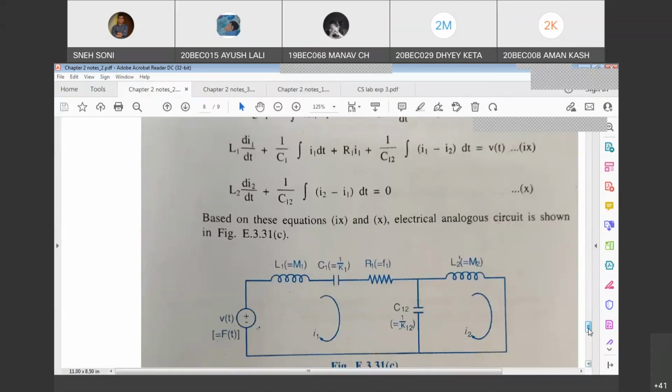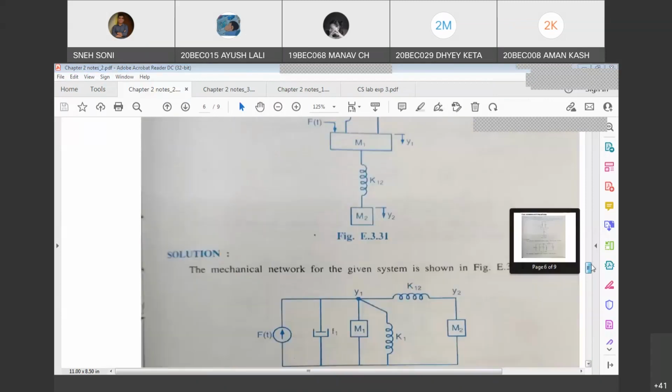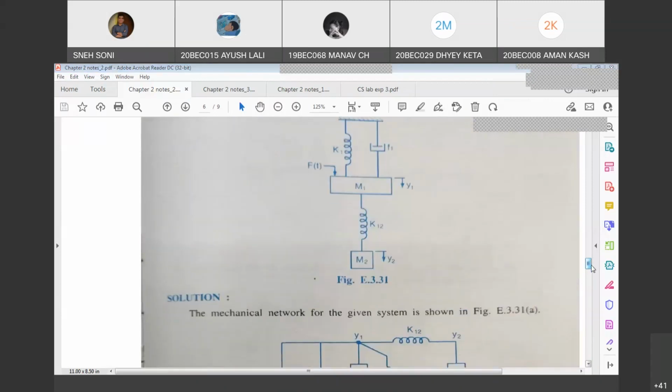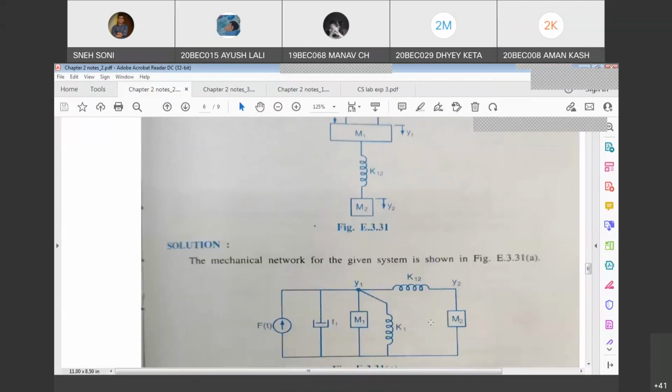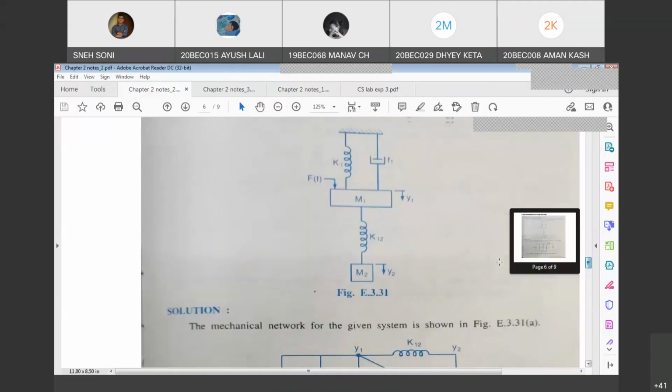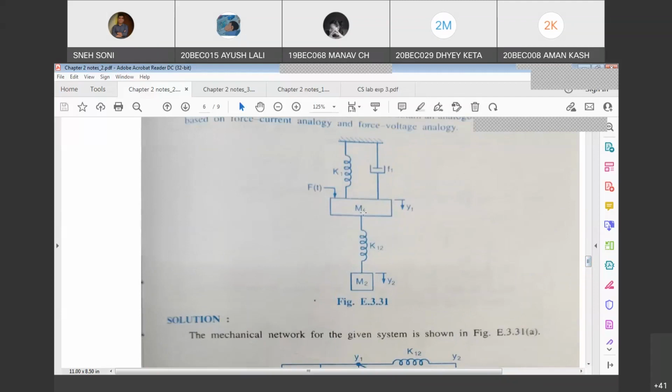Is there any difficulty? I hope you have repeated the same. Steps are very easy, right? As many masses as there are in the system, that many differential equations will be there. After that, you have to observe the system first. You have to see all the components, and then first of all draw the nodal diagram. And after drawing the nodal diagram, you go straight to writing the differential equations. So how we write the differential equation for M1 and M2, we discussed last time.